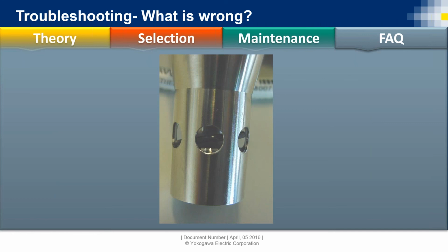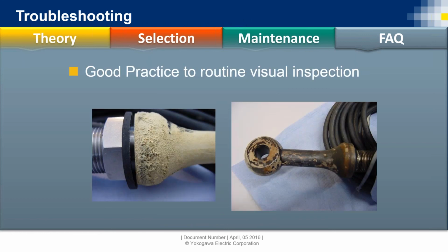And then this is one that I have come across in the past couple weeks. A customer couldn't figure out why the sensor wasn't working, and they sent me a photo of it. I don't know if you see it there, but there are internal O-rings in these sensors, and they have certain pressure ratings. So if we exceed those pressure ratings, or even if there's chemical attack on the internal O-ring, that's going to cause you measurement errors, because in this particular case the electronic side of the sensor wasn't sealed, so process was getting inside there and shorted the sensor.